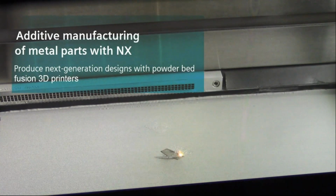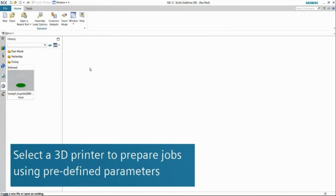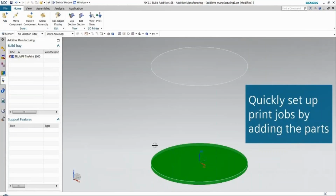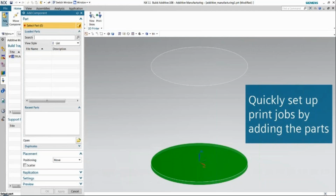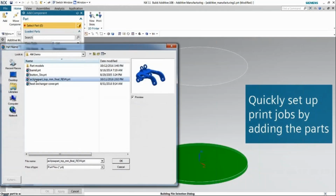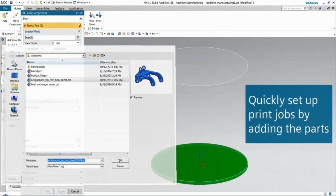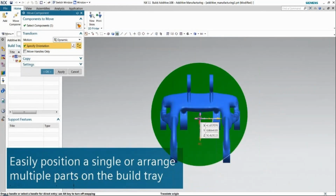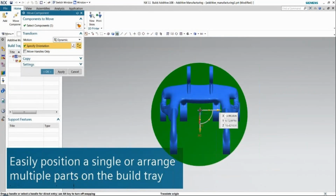Now, additive manufacturing for metal parts within NX, we can produce the next generation designs with the powder bed fusion. And this is the basic principle. You select your printer, you get the build tray, that's your build volume, then you're going to add components. And I'm going to be showing this same demo here later on in a different printer so that I can show the 3D nesting capabilities. Once you do this, you make sure that it fits inside of the build tray. Then you generate your code, and then you can view your slices.